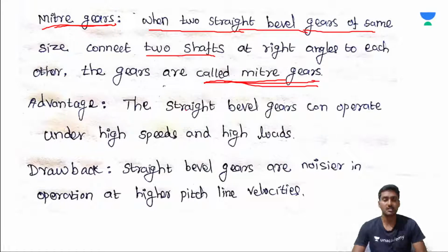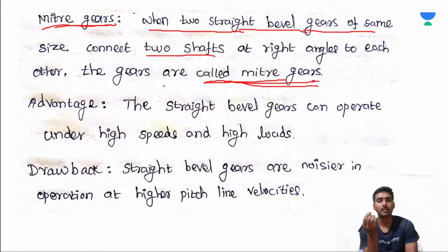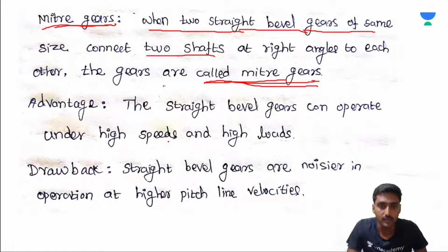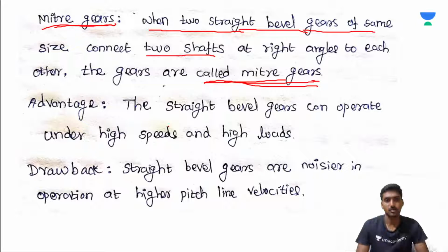Advantage: the straight bevel gears can operate under high speeds and high load conditions. Is it okay? And now, drawback: straight bevel gears are noisier in operation at higher pitch line velocities.